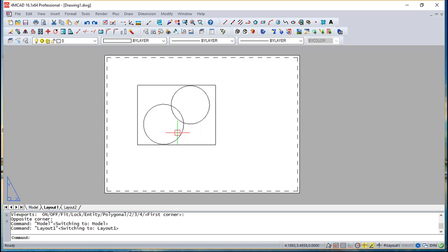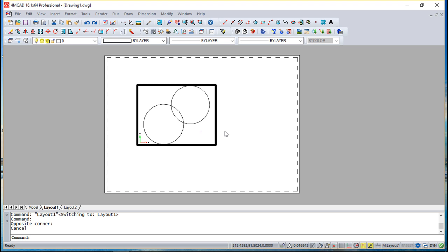But this has a special particularity, which is that this is not a rectangle. This is a viewport. If I click inside twice, you see that it was highlighted, and now I'm zooming with my mouse wheel, so I can put the scale or what I'm seeing where I want.